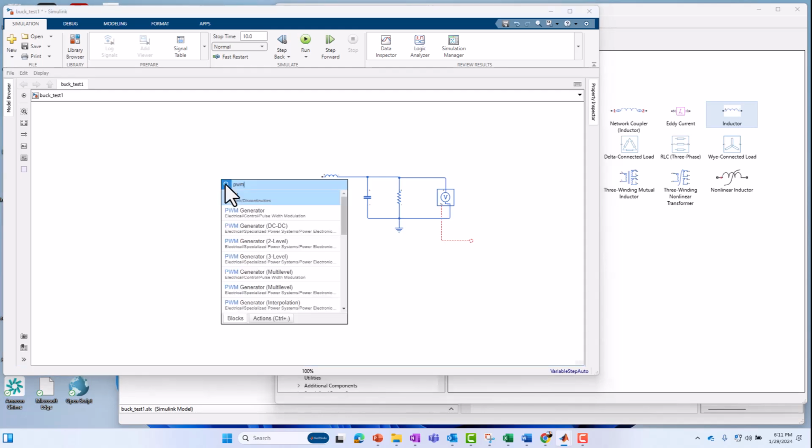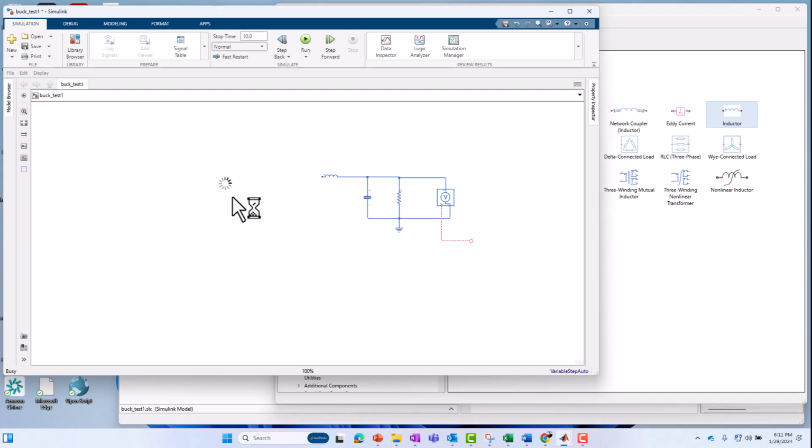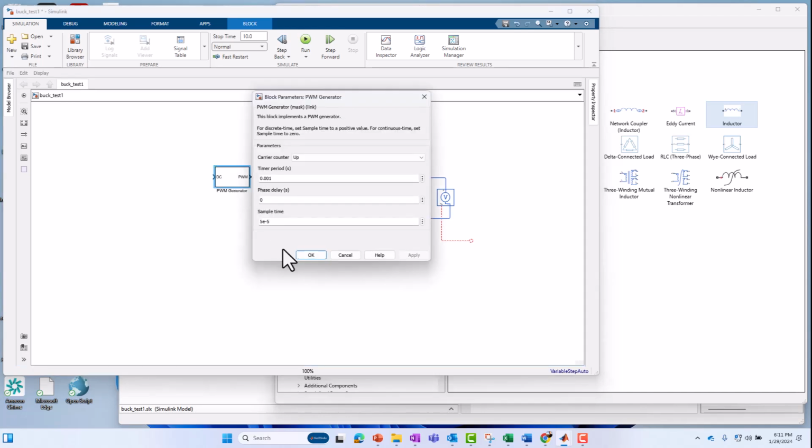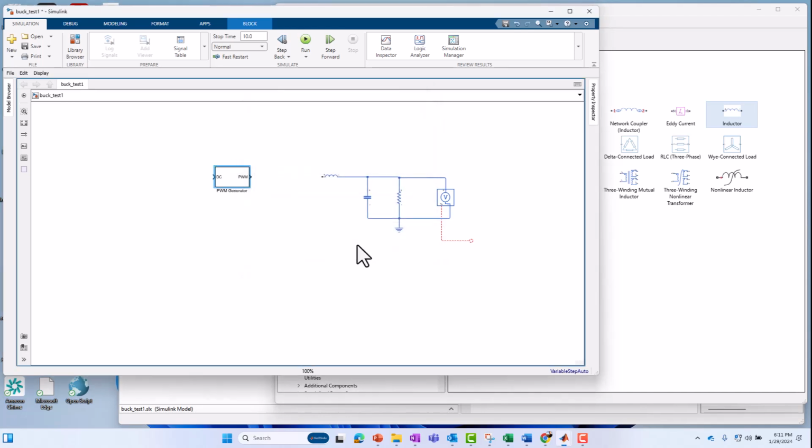and it just so happens that Simscape comes with a PWM generator. Of course, you could also create your own version of one, but I'm just going to use the one that's there at my disposal. And of course, all these blocks are parameterized. I haven't gone into these blocks yet. We're going to lay the model out architecturally first, and then we'll go in and parameterize and set its particular settings later. All right, so we're going to implement a synchronous buck converter in this case.